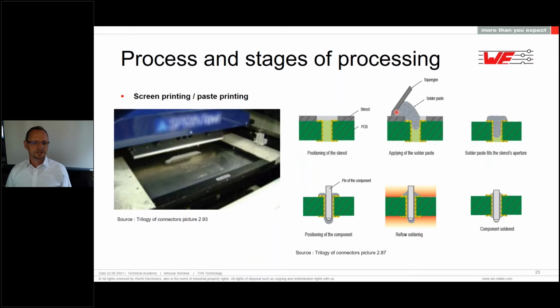Then your squeegee comes, running a kind of wave of the solder. So it's rolling the solder over here, and with this rolling effect, you push some of the solder inside the hole as well. And afterwards, you can run this also in 2 directions, yeah, back and forth.